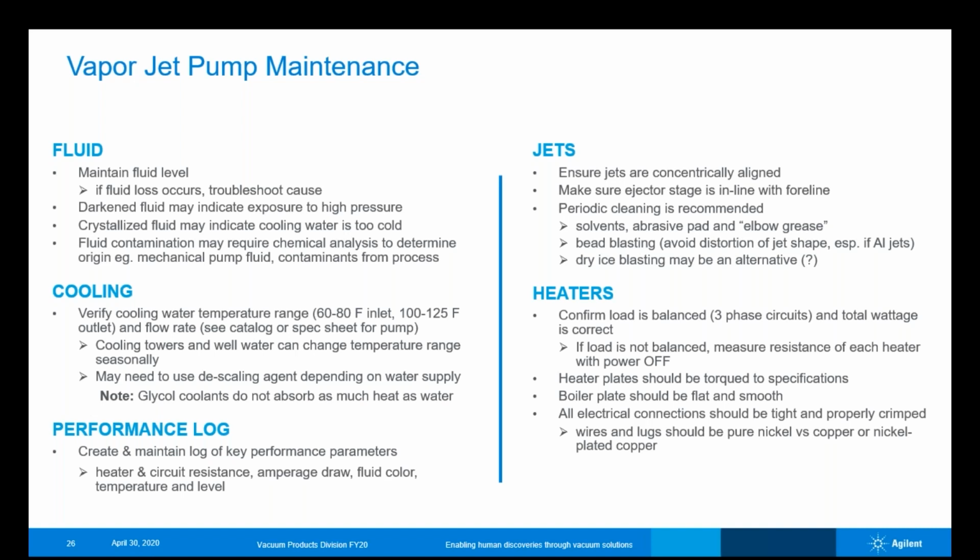And when we're cleaning, there's a couple of different schools of thought. There's use of solvents and abrasive pads, and just plain elbow grease, getting in there with some sort of abrasive steel wool or emery cloth, something like that, and cleaning up the surface of those jets. Bead blasting is pretty common, although we need to be careful not to distort the shape of the jets, because that's going to influence what the shape of that cone of high velocity oil mist coming out of the pump is going to look like. And any breakdowns in that are going to create, let's say, a leak path for gas molecules to go back towards my chamber.